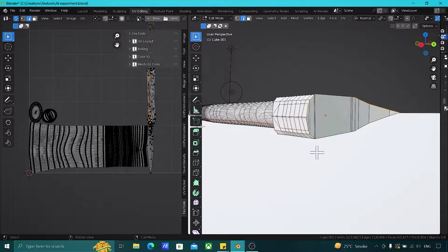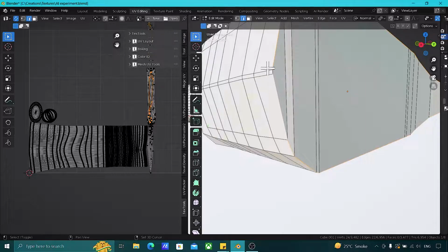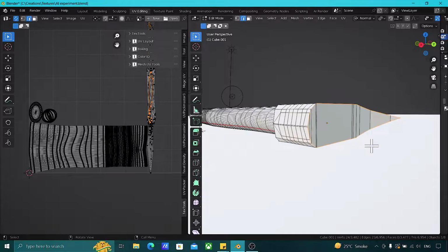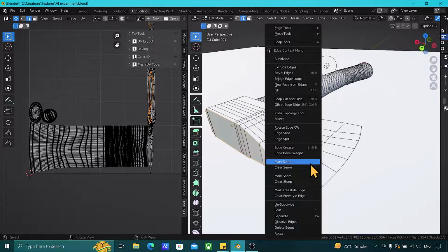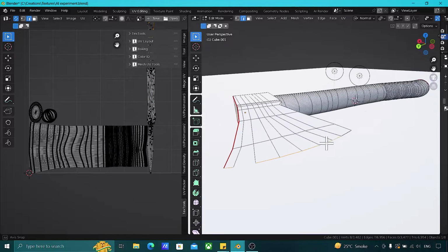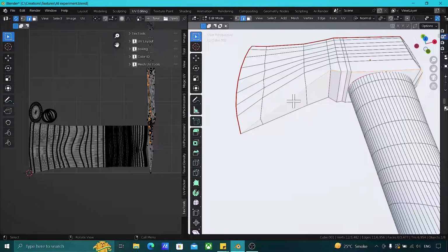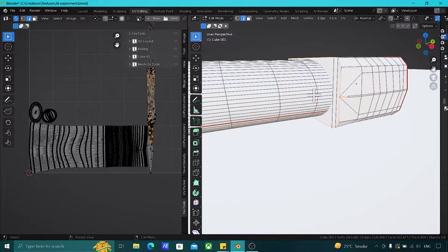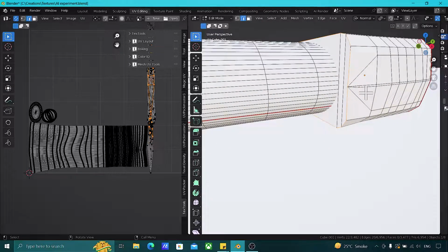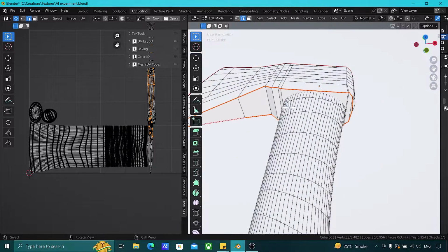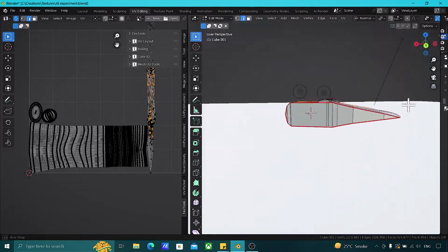All right, so what we'll do is we'll pick this, and remember, these small spots are very important. If your complete seam is not connected, you won't be getting that unwrapped. All right, so I have marked it as seam. We need to pick this, mark seam, below portion as well. We need to pick this, make sure that it's properly selected, see, this is the extra area that we need to deselect by pressing Control, and we need to press on mark seam. All right, I think we are good to go for now.